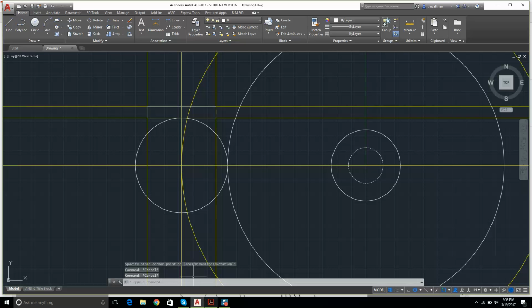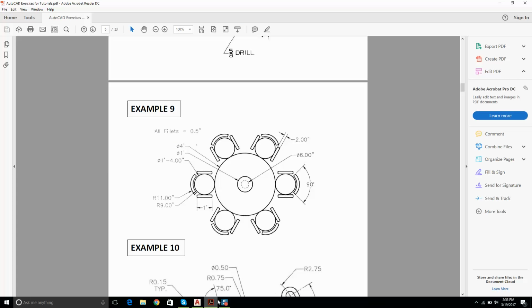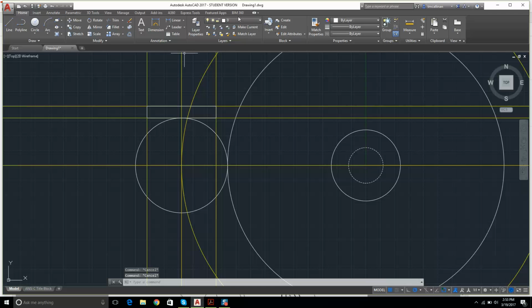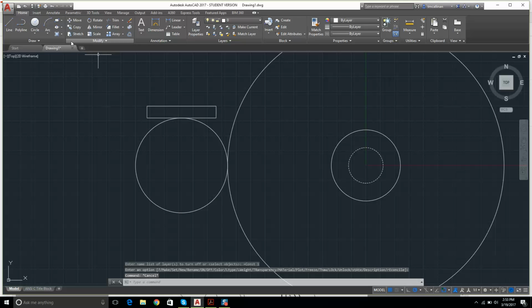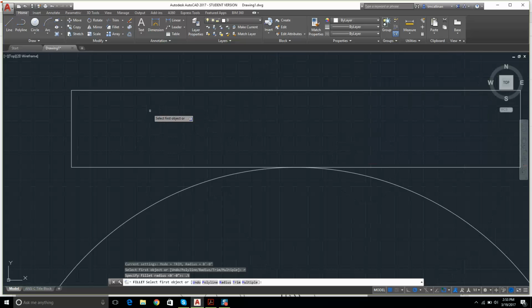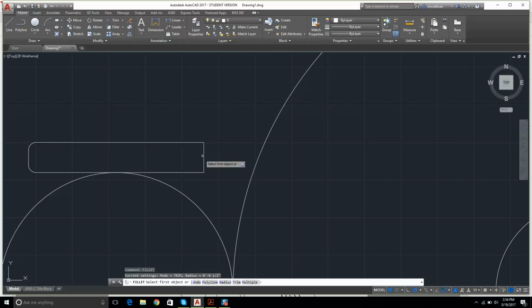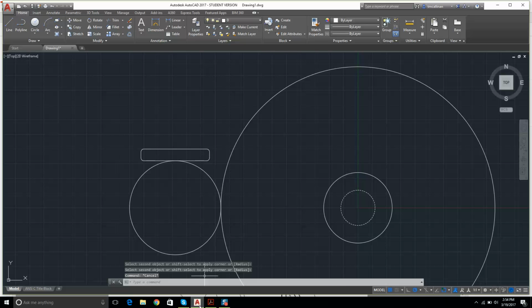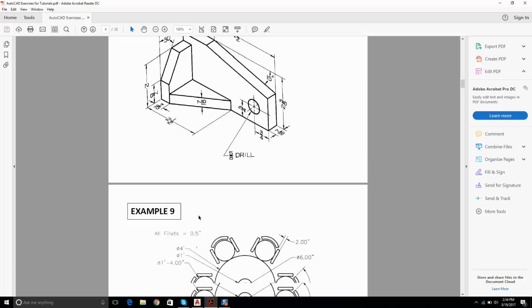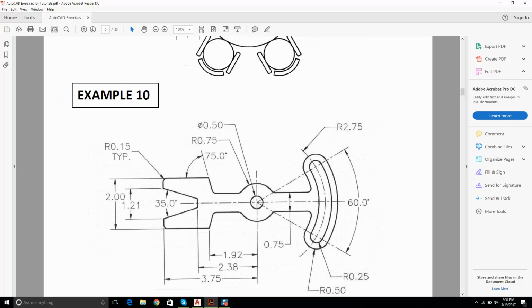Okay, I got that. We have to put little fillets on that. I feel like they're just a half an inch. So let's put them in. Fillet, R for radius, 0.5, then 1, 2, I hit up, enter, 1, 2. You can do multiple if you want to. Up, enter, 2, up, enter. Okay, now let's go back here. Drawing one of these chairs is a real pain. This is why we're going to array it.